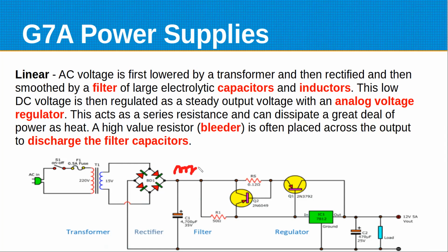That kind of waveform. There's a filter capacitor. Sometimes this could be multiple capacitors in parallel and possibly a series inductor to help filter this out, depending on how clean they want the signal to be. These transistors are kind of a helper circuit for this integrated voltage regulator.